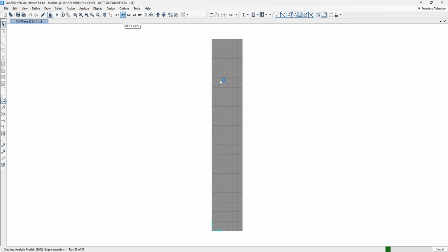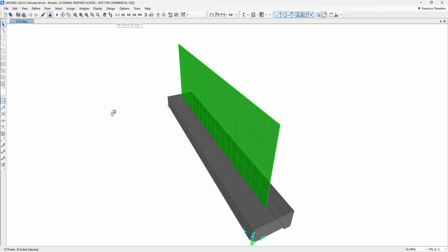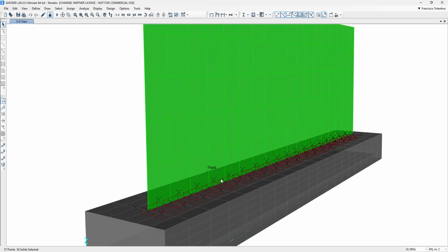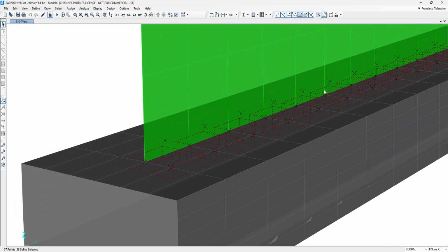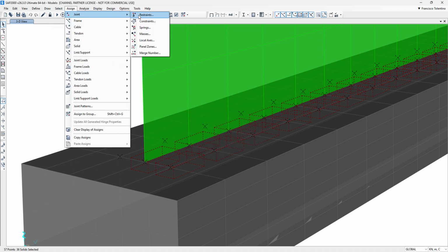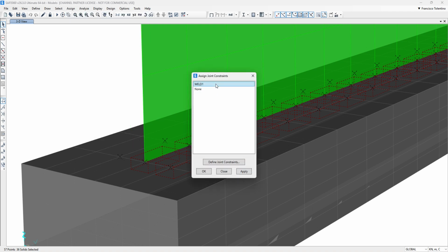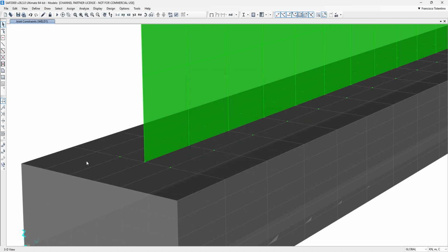In short, the idea is that each set of 3 nodes behaves like a rigid body, independent from the others. This local rigidization is not global. It only binds those 3 nodes together, so the wall can still deform realistically along its length. This way, the 3 nodes working together force the inner node to develop rotational stiffness, driven by the vertical displacements of the outer nodes. Thus, we ensure a fixed base condition for the wall. Functionally, this mimics a kinematic link that transmits bending continuity from the shell into the solid foundation.